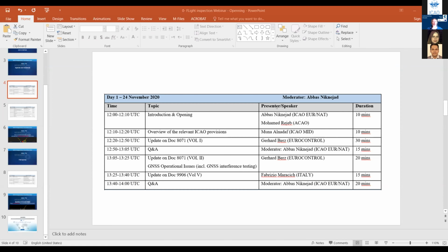If you talk about calibration by the CNS, it's a mandate of ANSP. But if the question is about flight inspection, then what we as ICAO USOAP auditors expect from Civil Aviation Authority inspectors is to keep monitoring the procedures and the implementation of Annex 10 requirements and Doc 8071 guidance regarding flight inspection during their regular Civil Aviation Authority inspections over the ANSP and over other service providers.